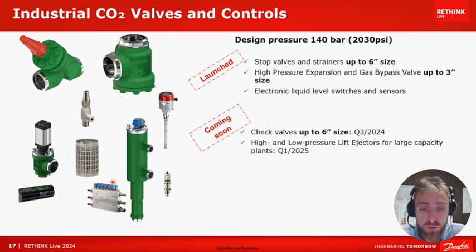We have had for several years now our multi-ejector available in Cool Selector. This was targeting commercial and food retail applications when it was developed. But if we want to grow in size our CO2 heat pumps, then we need larger ones. Therefore, in the last couple of years, we have been developing our industrial size ejector, this one over here, which will be launched next year and will be able to support our partners to build racks of several megawatts size. One of these components becomes relevant at capacities above 600-700 kilowatts, and you can have many of those in parallel. This is coming soon, and already now we have opened a couple of projects in the field with it. This will save energy and will really support the industry to gain more efficiency.